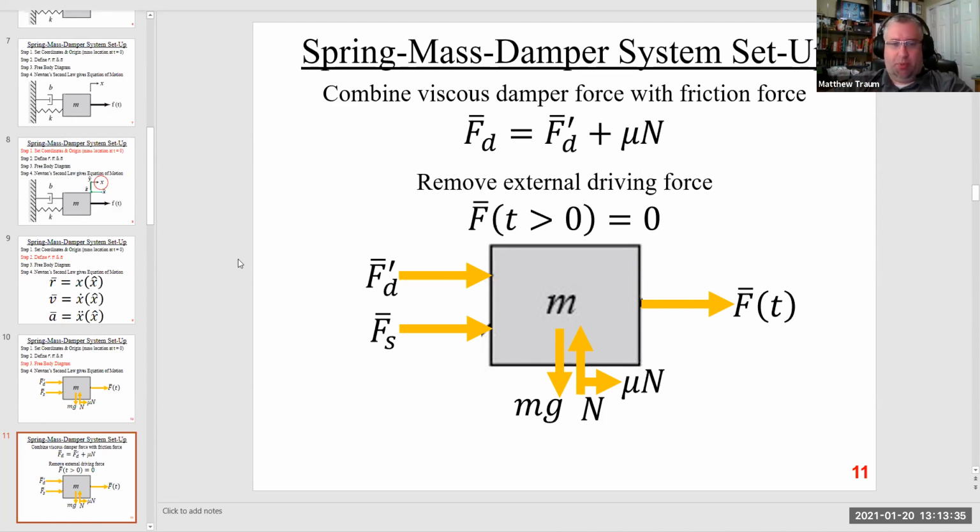In spring 2020, the RER artifact was an RC car shock absorber, and the shock absorber, of course, had a spring in it, but it also had a built-in damper, which was literally just a hole drilled through the piston. And as you compress and decompress the shock, the piston would move up and down, and the fluid, which was a kind of hydraulic oil inside the piston, would just slosh back and forth from one side of the piston to the other through this hole that had been drilled in the piston.